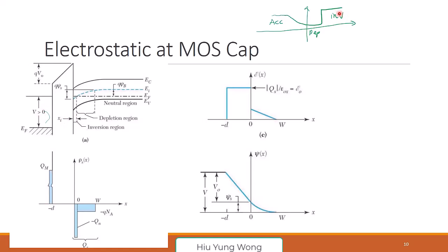But how do I see that? You see that the band is bent here. So actually, the Fermi level is here. So you get more electron, right? So at high positive bias, you get positive charge on the gate. Then you have the depletion, and then it has the inversion. Sorry, I said the thing wrong. It is inversion here. Is that okay?